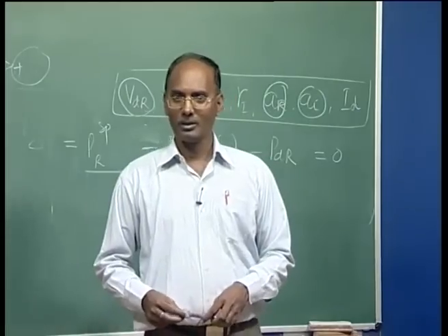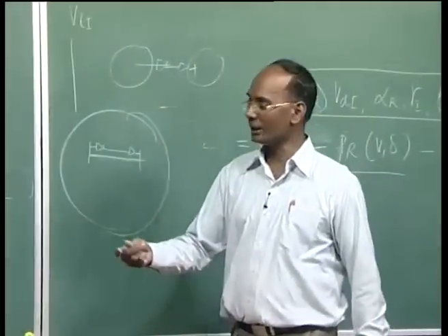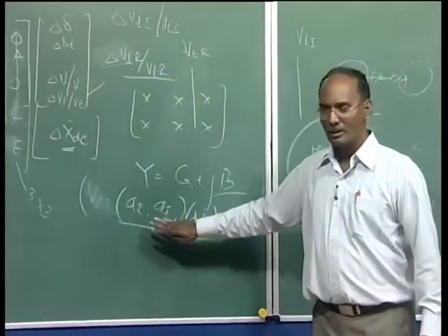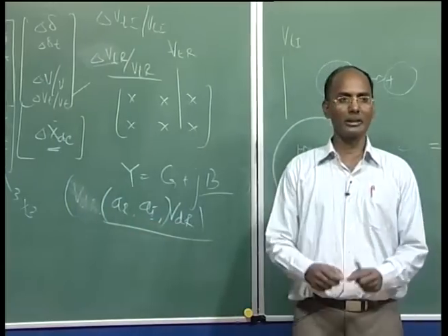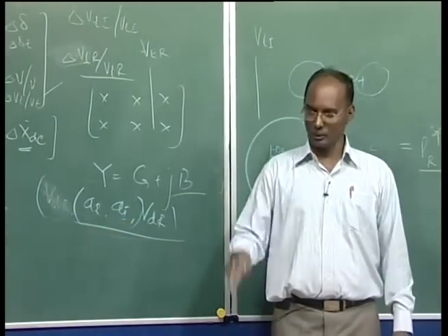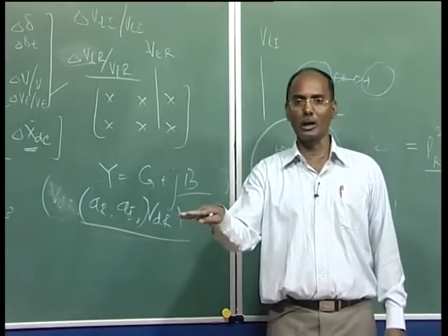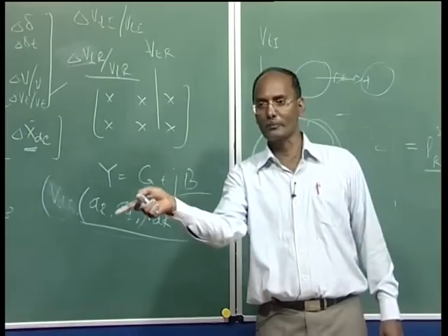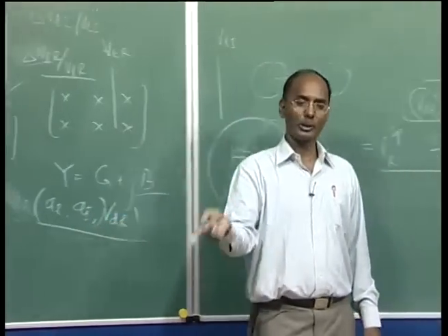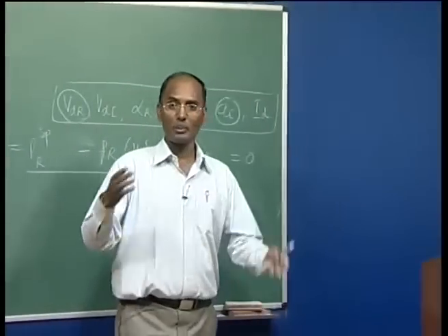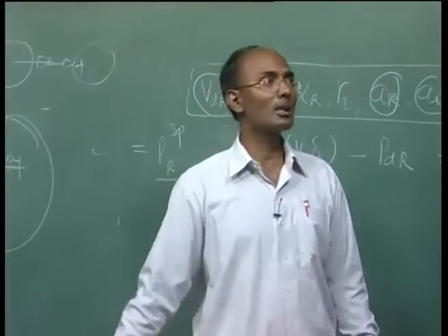So, these are dynamically changing, sir? Yeah, it will keep on changing if it hits some limits. Let us suppose your tap is hitting a limit, you calculate the tap and it comes out absurd, so you have to fix that value. Now the tap is known, and it will go into a different control mode. So it basically keeps on changing, like your PV and PQ buses. Here also it will keep on changing and then we can calculate E.